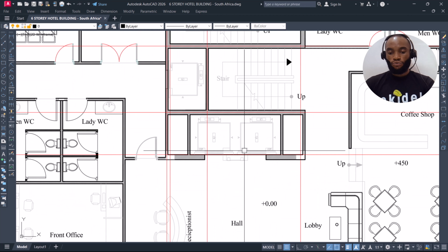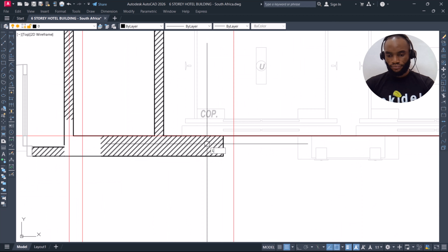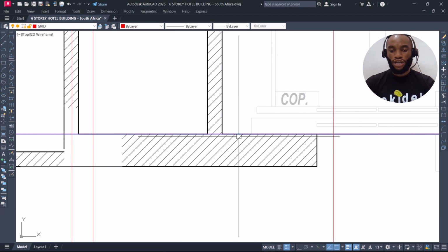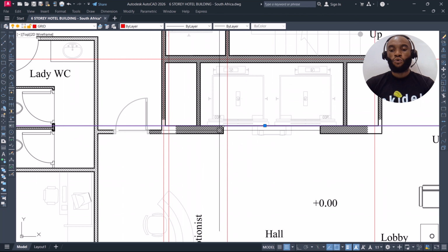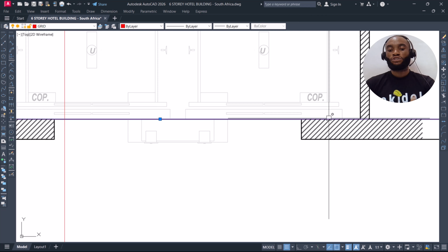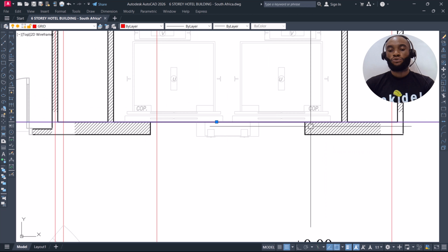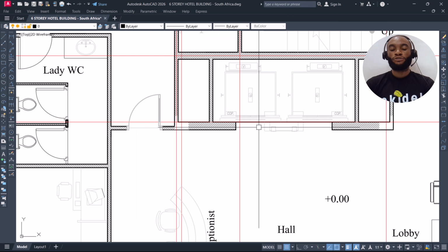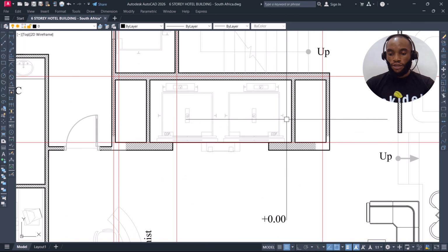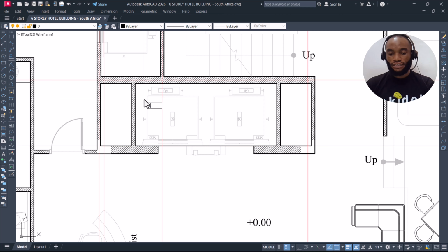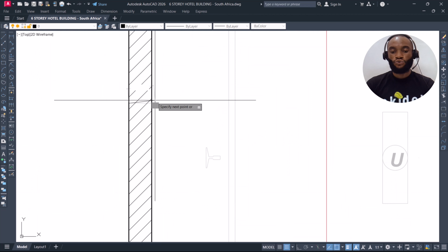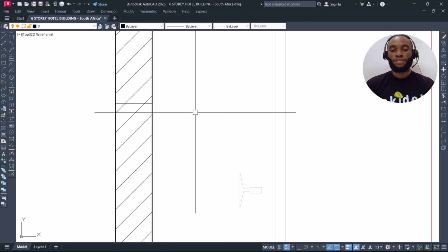So again, we also need a wall here. Let me see, we already have a wall here actually. So we are going to place this wall and then make the wall to align outward. So we are not going to place another grid line here for this purpose. Okay, that is fine. So again, we need to create a grid line for this lift wall on this side. These are the two grid lines we need to create, and then we are done with the grid lines stage.